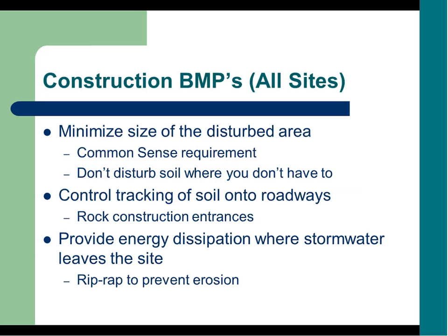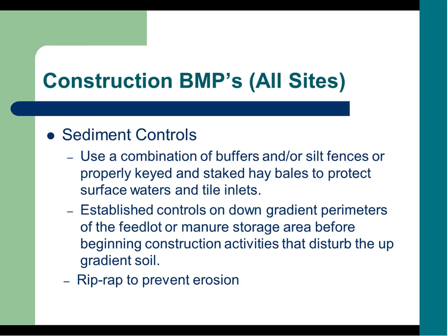Construction BMPs for all sites. We're hoping it's common sense. Minimize the size of the disturbed area. Don't disturb soil you don't have to. Control the tracking of the soil onto the roadways with rock construction entrances, and provide energy dissipation, riprap or bales or mulch or some sort to keep things that are leaving the site from causing erosion.